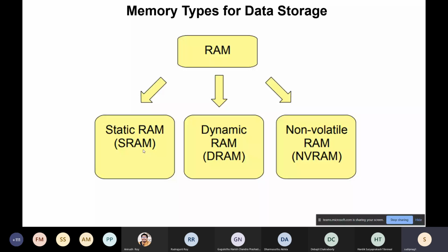Now, the third type, NVRAM, which is the very latest one, is offered in very few embedded microcontrollers. NVRAM is non-volatile RAM. Now I said RAM is volatile, but NV is non-volatile by name itself. So NVRAM actually breaks the barrier of the RAM and goes into the non-volatile space. It's a type of RAM which can be read and even written and erased for millions of cycles.